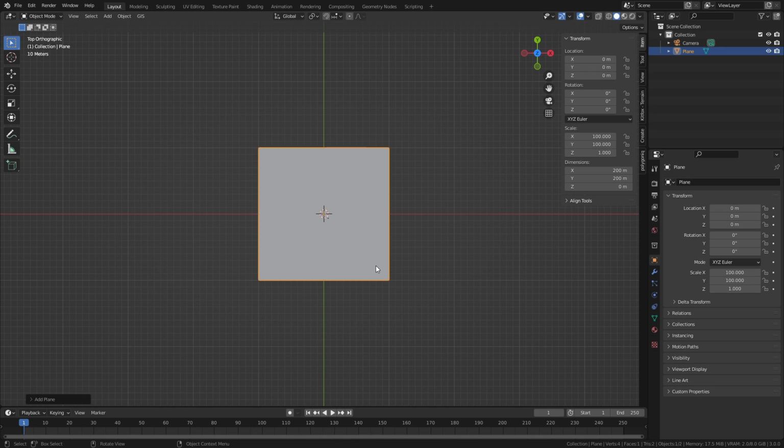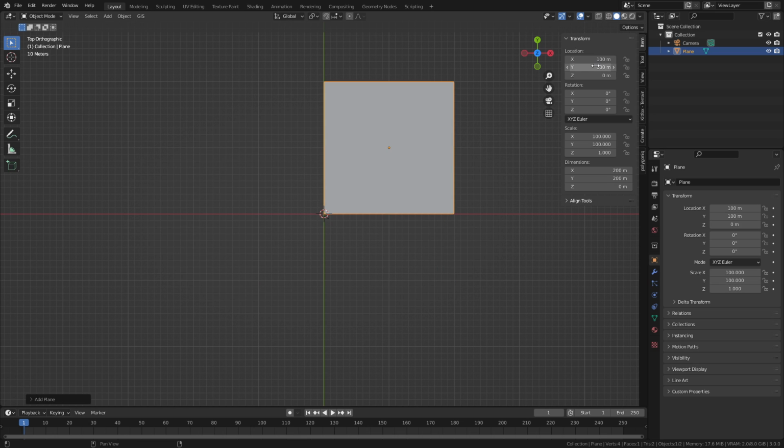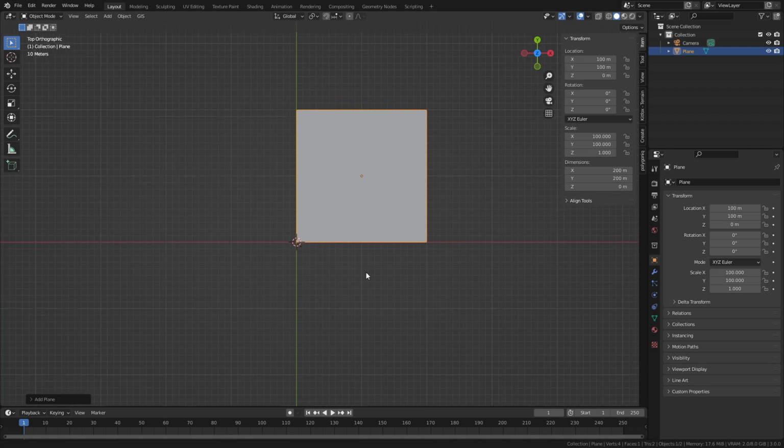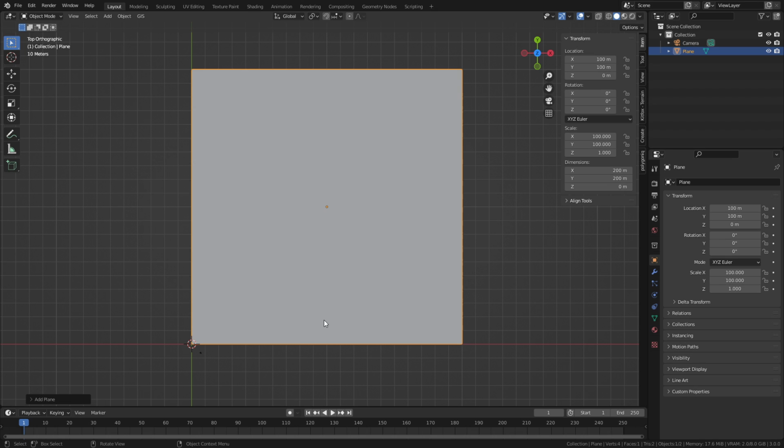However, if you're going to use this blank plane as the start of your Supercross track, or this is how I did my Enduro Cross track, you want to move that bottom left corner up to the origin, so then when your height map is rendering, and when you place objects on this map and export those out, they're going to line up correctly on your track in MX Bikes when you build it. So let's go ahead and do that. We are just going to move it really easy. You can just go half of 200, which is 100 over and 100 up. So now our 200 by 200 meter plane has the lower left centered on the origin, and that's how we need it for use in game to make it easier.